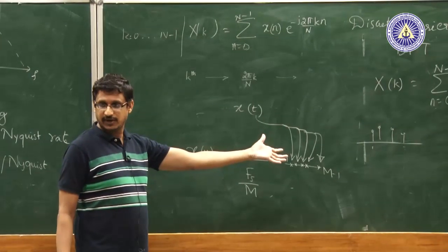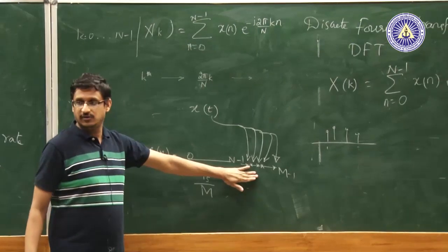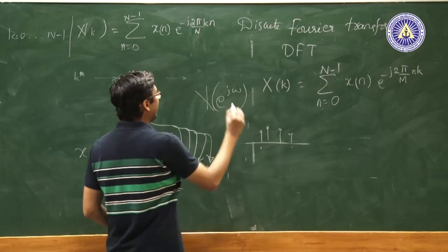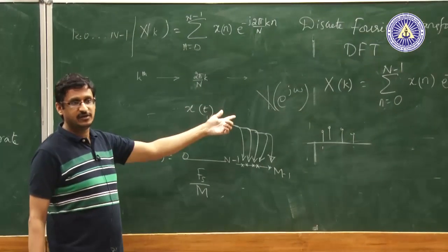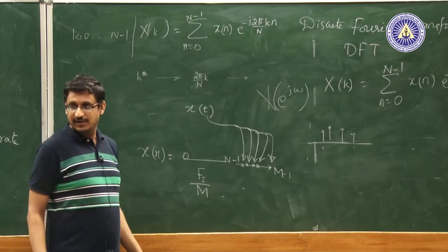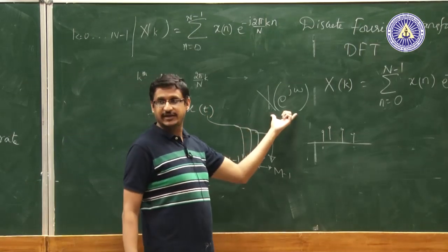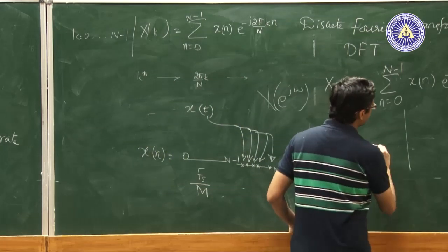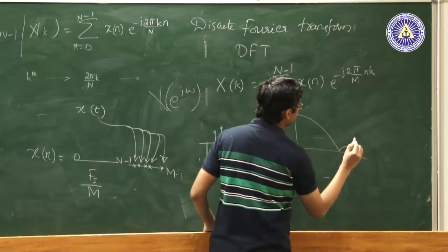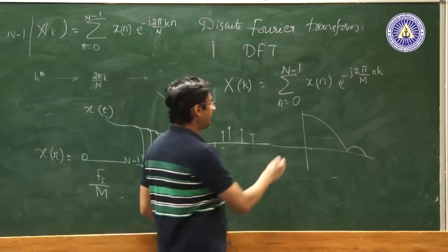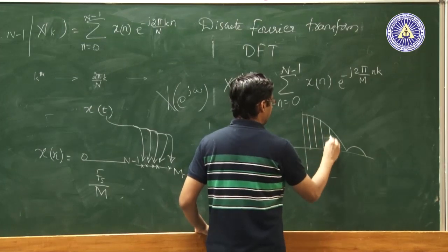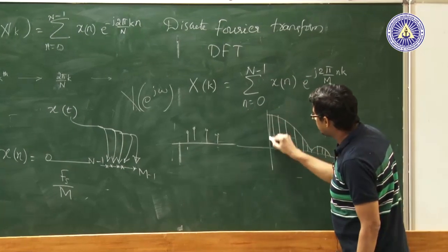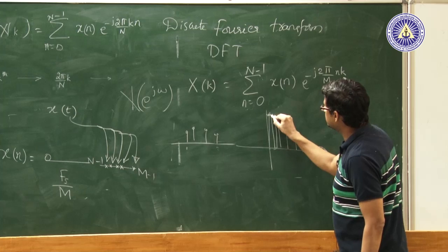the correct DFT, right. Where will this be useful? Suppose you have an original DTFT, which is X(e^jω), and then you want to sample this original DTFT with a nice looking picture. In that case, instead of taking n values, you can take m values, pad them with zeros and then sample. Suppose X(e^jω) originally looks something like this. With n, you would have sampled them here, but now with zero padding and increasing m, you would have sampled at these values in addition to these values.